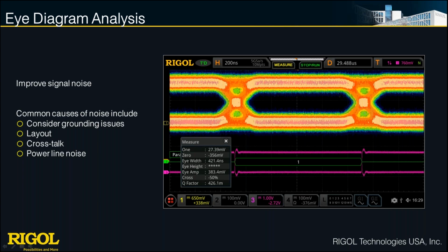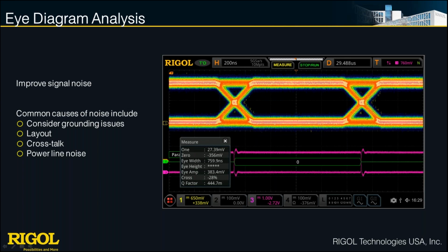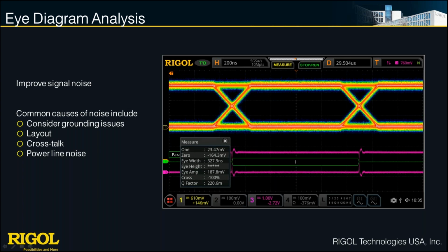And as we work through that, we can improve the noise and start to see the true signal come through as we are able to get rid of a lot of that amplitude noise. So here's a signal where we've got very little amplitude noise remaining, pretty nominal, with good timing and good amplitude noise. But the crossing patterns here still show possibly some issues with our signal bandwidth. So now let's move and try to optimize our signal bandwidth.